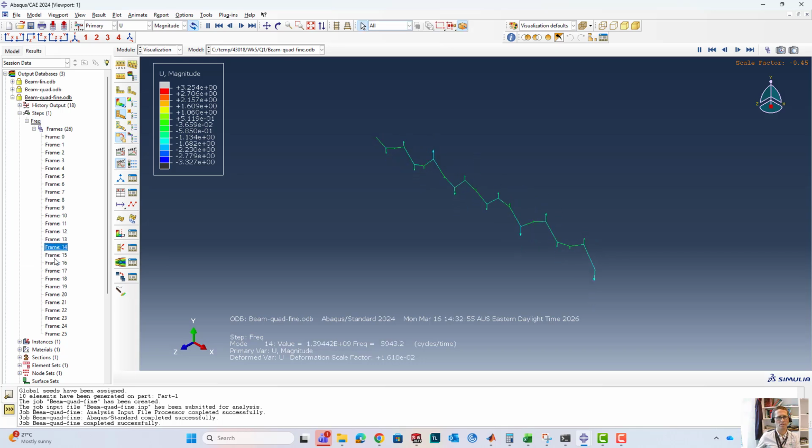And at some point we start to see some spatial aliasing. That's our second longitudinal mode there now, with a nodal line partway along, and so on. Okay. Third longitudinal mode with 2 nodes. Fourth longitudinal mode.